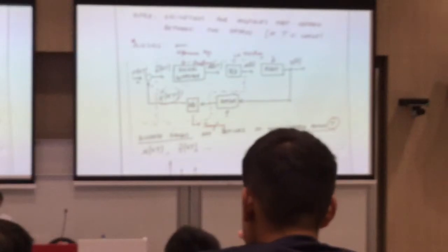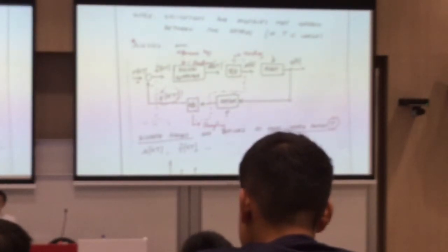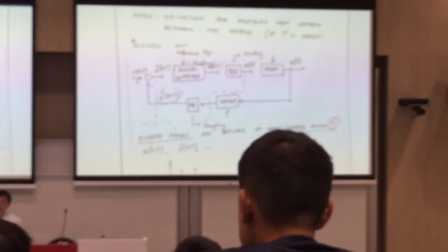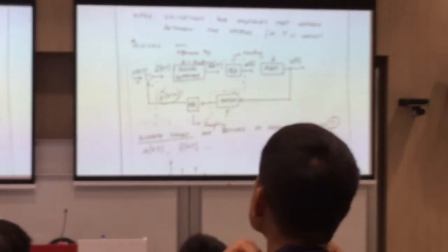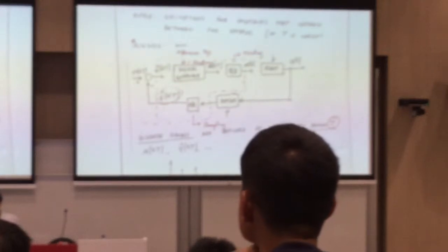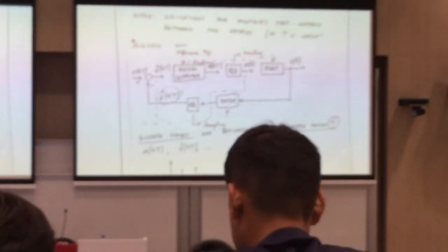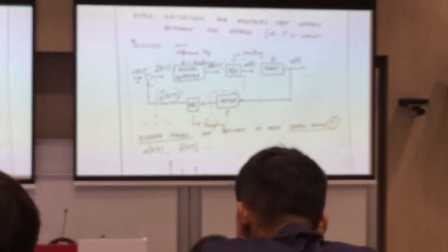What do we mean by digital controller? A digital controller means you are going to use difference equations rather than differential equations, and you are going to use z-transforms rather than Laplace transforms. This is something we spend about 2 chapters on later, about the difference equations and their transfer functions. And after you get your output from your digital controller, your output itself is a digital signal.